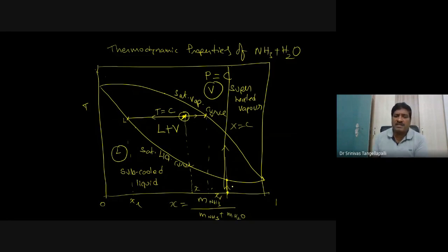Assume this is the economizer in case of the boiler. Okay, in the boiler, what is happening? The temperature of the working fluid is increasing. At the end of the economizer, the working fluid temperature has reached the saturation temperature. Okay, we enter into the next component, the evaporator.